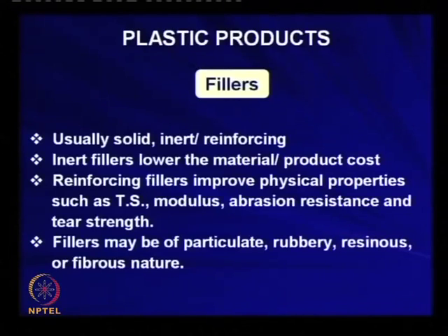So, inert fillers do not interact with the polymer chain; they simply remain present within the polymer matrix, and they reduce the cost by increasing the volume. It is known as inert filler. It will decrease the mechanical properties: it will decrease the tensile strength, and it will increase the modulus of course, because the modulus is a low extension property.